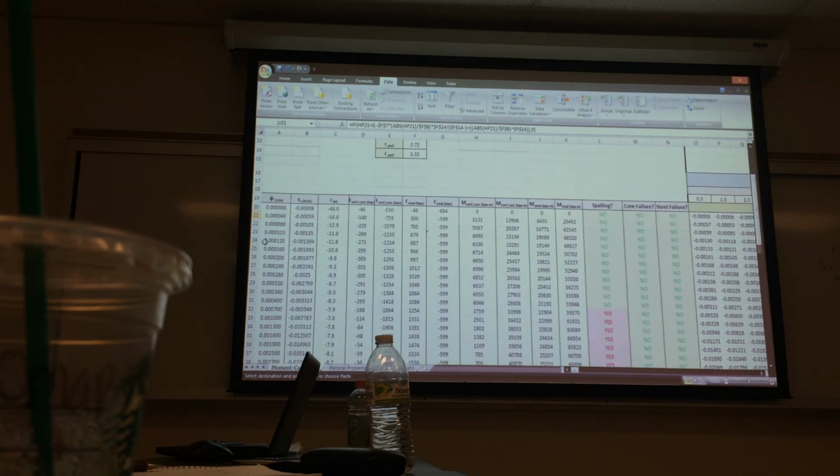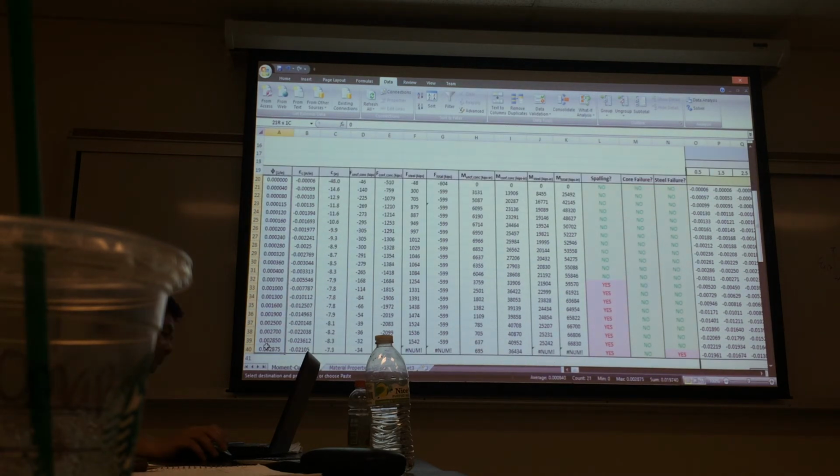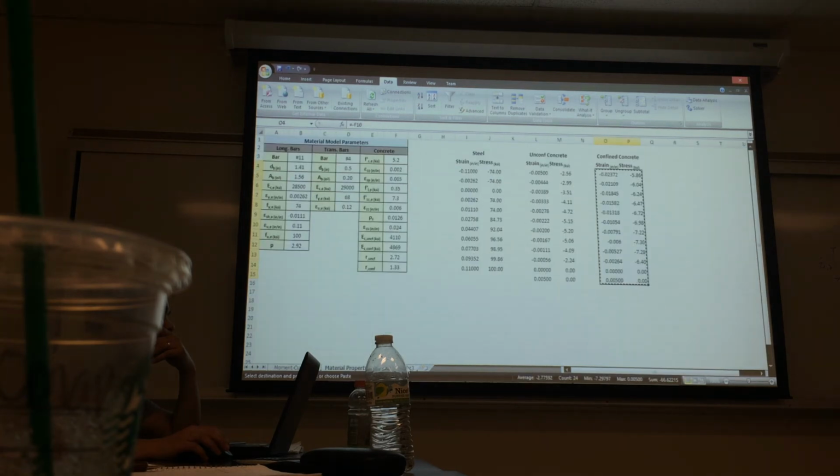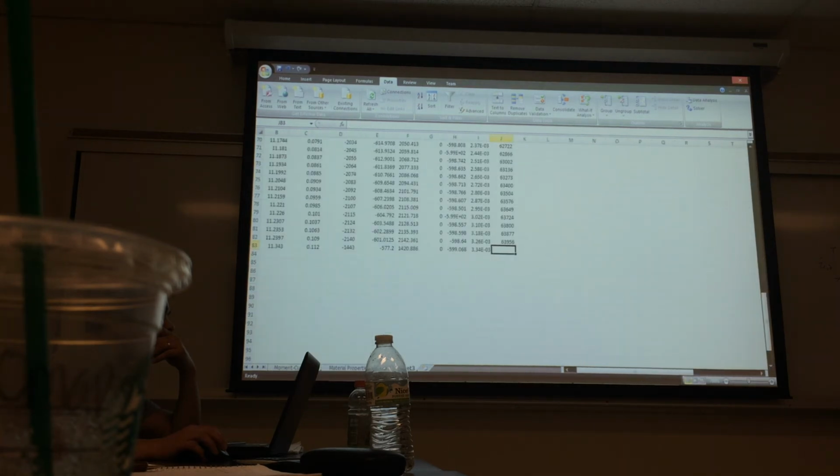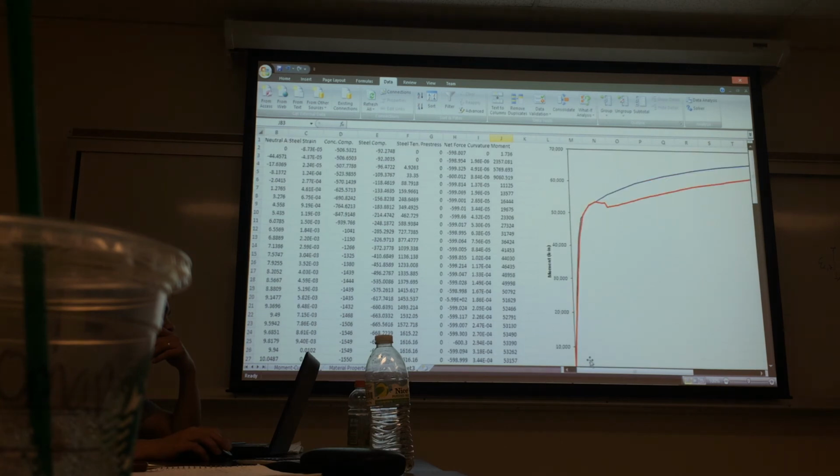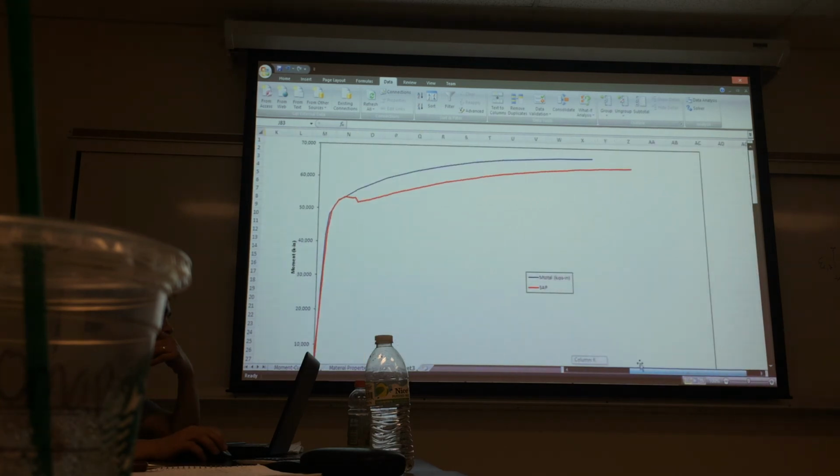And then it would go through and run this whole process where you're looking at curvature, these different increments, and it iterates the compressive strain, and it gives you a section moment capacity based off that variable. And you'll get stuff that, even by doing this discretized fiber modeling, matches pretty closely with SAP.